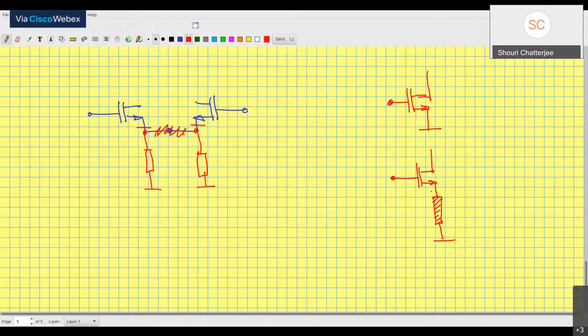All right. So that is why we place a current source over there. Now you would say, why place a current source? Place a very, very large resistor, right? Unfortunately, it's not going to work, because if you put a very large resistor over there, you won't have any swing. Remember your swing limits. Your swing over here is going to be severely limited because you need to have a certain current over here. But if you have a very large resistor, then this voltage becomes very large. All right, so you really can't have a very large resistor.